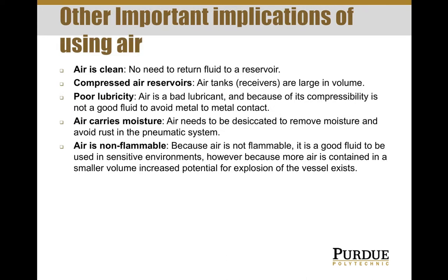And then some other important implication: because air is clean, you can dump it back into the atmosphere without needing to have a reservoir. You can just do that and no problem, no filtration needed. Compressed air reservoirs, or air tanks or receivers, are typically large in volume. They need to occupy a large space if you want to store some energy. It's just the nature of things, because air is very compressible. You need a lot of volume to store some energy.